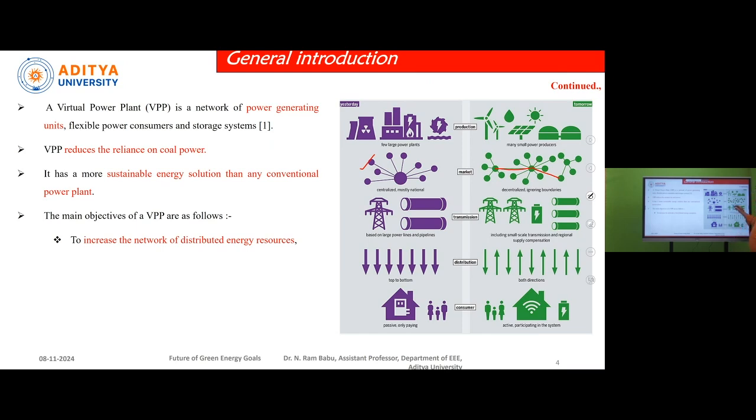Apart from that, the conventional system has long transmission lines for overhead transmission and underground cables for underground transmission, and in the decentralized system battery energy sources come into the picture. Whereas in conventional or centralized power stations, battery storage devices are not considered. Here you can assume an electric vehicle system or a battery storage device which stores energy from solar PV cells or wind turbine systems, storing energy in off-peak hours and selling it during peak hours. So in the decentralized system, batteries will be considered.